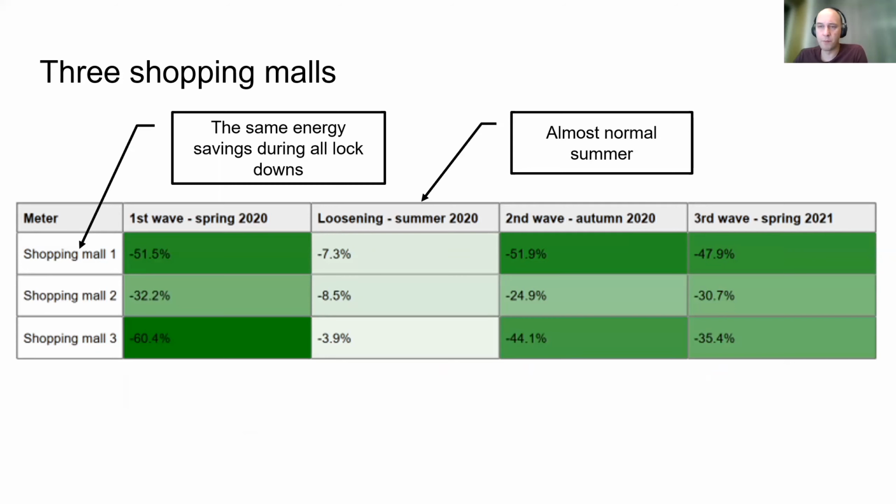The most important part is to have some valid weather forecast and also forecast of all independent variables. It means mainly if you have, for example, different models for occupied and unoccupied periods, you need to know the occupancy profile in the future. If you have this, it's very easy to provide the prediction, and the reliability of the prediction is determined by the reliability of your inputs, so by the reliability of your weather forecast.